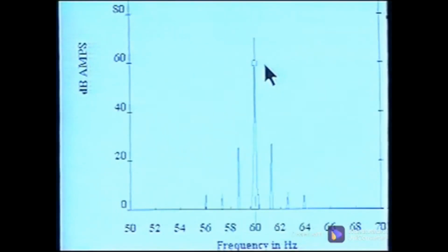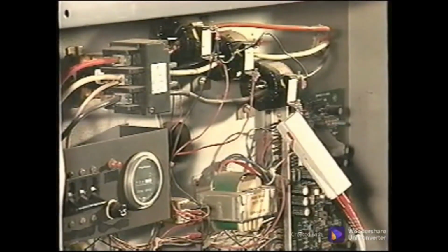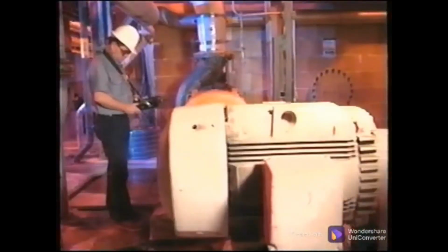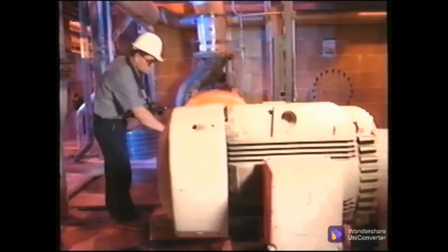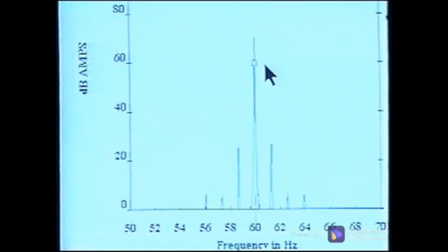To maximize these current measurements in an RBM program, the current measurement should be used in a similar way that vibration measurements are used. That is, collect one reading when the unit is put into service to use as a reference. Then continue to collect vibration data and trend it for changes. When changes are detected in vibration data, collect another current spectrum and check for rotor bar problems.